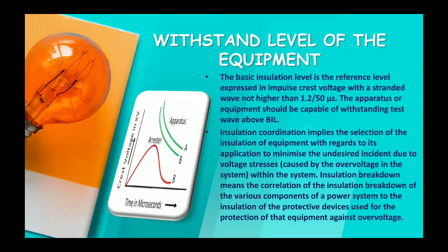Insulation coordination implies the selection of the insulation of equipment with regard to its application, to minimize the undesired incidents due to voltage stress caused by overvoltage in the system.